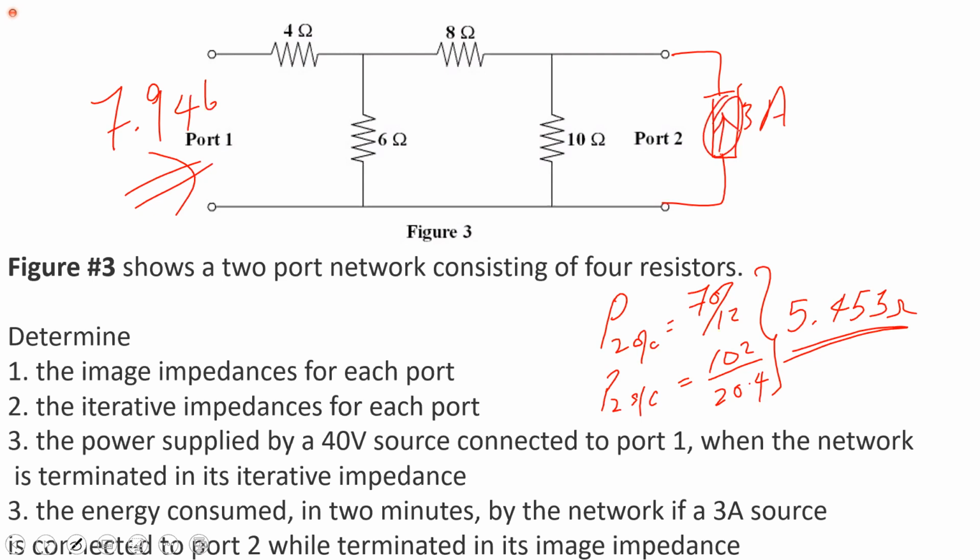Yes, sir. We'll have the impedance would be the 10 in parallel with the 8s and 6. Well, so I'm terminated in the image impedance. So what impedance am I seeing? All right, let me ask you. What I'm really asking is for you to use the definition for image impedance.